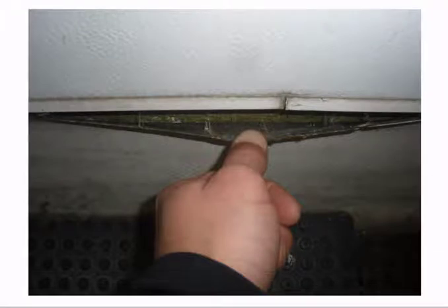So, Craig, looking at this picture, looks like we've got a flashing that's clearly problematic. What do we see? Well, what I don't see is a termination bar or water cutoff, the mastic you put behind there. Those are the two key things to a flashing. For the basic flashing detail, water cutoff and a term bar to hold that membrane. Neither one of those are here, so that's going to allow water to migrate in behind that flashing and enter the roof system. What might we do if you run into this in the field to repair that?